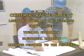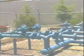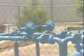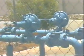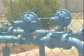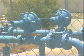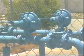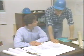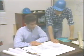Hazards that are peculiar to the specific process must also be considered. For example, characteristics of reactive process fluids require a thorough investigation to determine exactly what hazards exist. Examples of such materials include oxygen, hydrogen sulfide, chlorine, and acetylene. So you can see there are many considerations that must be given to fluids other than their toxicity.